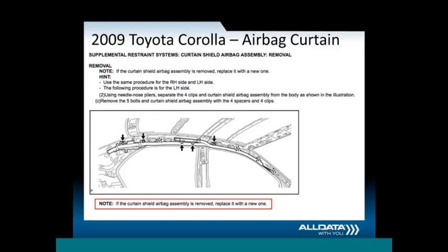Let me give you another example of something that I found recently with AllData. Many of you, I hope all of you, are aware that you can never weld within 12 inches of any electrical component. Some vehicle manufacturers even say 18 inches. The reason is that the average car battery is 12 volts, and the average charging system in a vehicle is designed to handle up to about 14.3 volts.